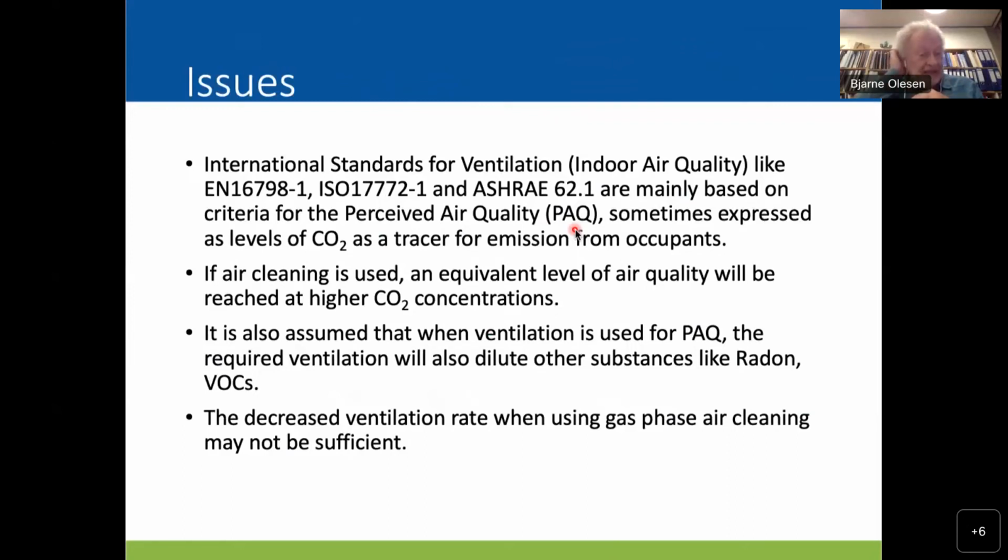So the standards which are going to use the results are the international standards for ventilation, where we have an EN, we have an ISO, there's also ASHRAE. And the required ventilation is mainly based on perceived air quality. But sometimes it's also expressed as a level of CO2.